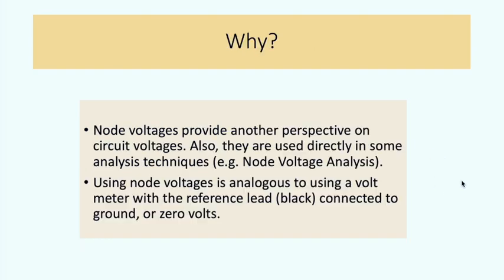Okay, so why do this? Why do we need node voltages? Well, first of all, they provide another perspective on circuit voltages, and they're used directly in an analysis technique known as node voltage analysis. Furthermore, node voltages are similar to what we would measure when using a voltmeter with the reference lead, or black lead, clipped to ground.